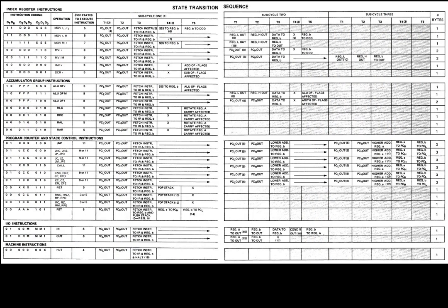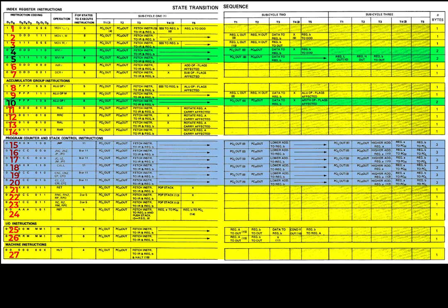the entire 8008 library. From it, we can see the 8008 has got 27 instruction groups, and we can see that there are 18 of these that are 1-byte instructions. There's 3 that are 2-byte instructions, and 6 of them are 3-byte instructions. And we'll revisit this table as we bring up other aspects of the 8008 processor states.